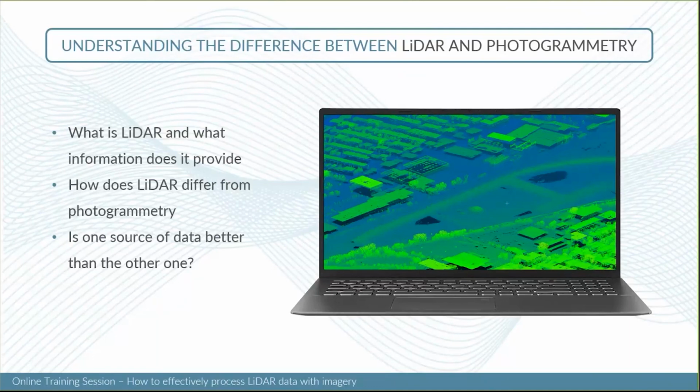However, there are a few disadvantages compared to photogrammetry. The first one is probably the cost. The cost of such LiDAR equipment is really high compared to a UAV. Photogrammetric data is much more accessible to everyone, and the cost of the software is less expensive. Also, you could do photogrammetry processing with really low-end UAVs, and it's available for everyone.